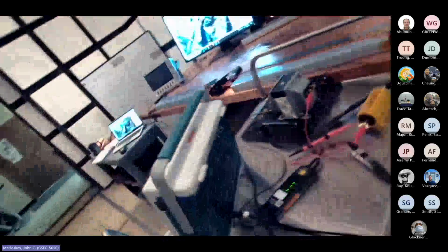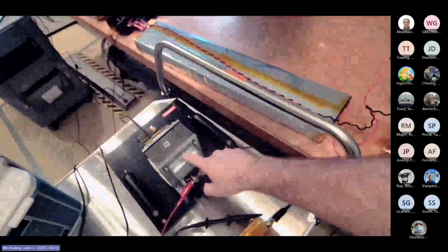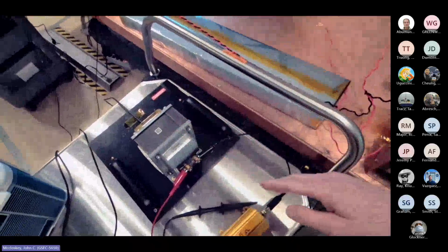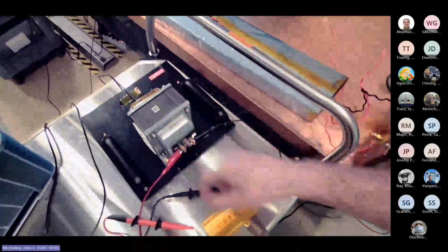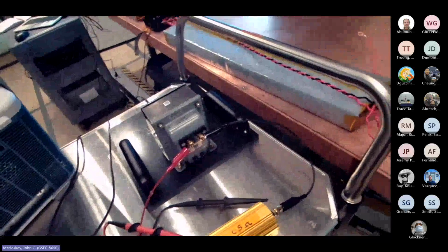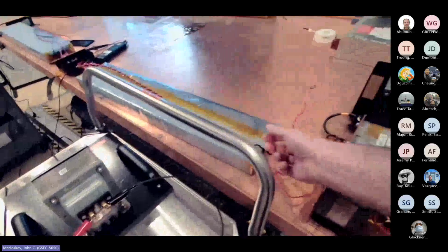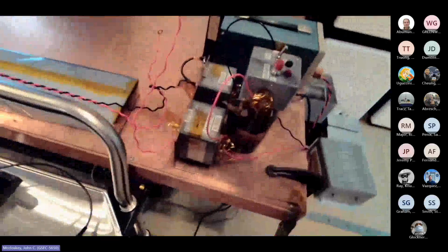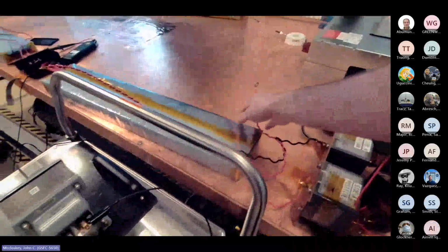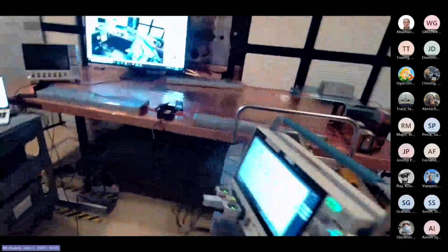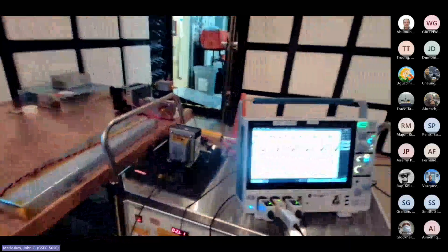Now for the CS101 setup, the heart of it is the injection transformer. I'll go around to the front and show you the model number. It's basically the standard injection transformer used for CS101 and CS01 before it. Eventually, we're going to hook it up in line with our power feed, with the red wire coming off our capacitor network. It's disconnected now because we're going to pre-calibrate first. We'll come back around here in a moment.